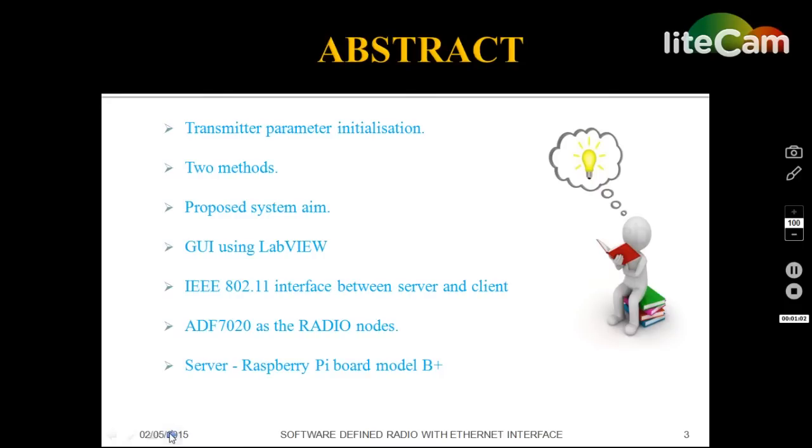Our project aims in developing a GUI using LabVIEW to set parameters for transmitter initialization. Our radio nodes are ADF7020 transceivers which are controlled by PIC microcontrollers. This LabVIEW based GUI acts as a client and radio nodes together with the Raspberry Pi acts as server.